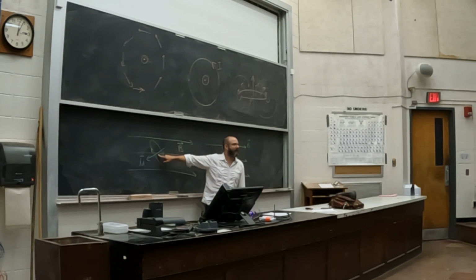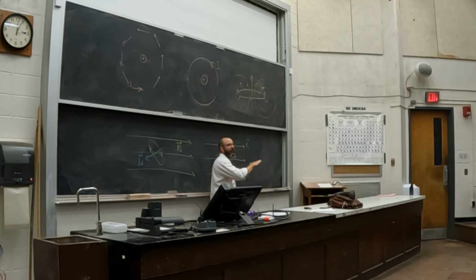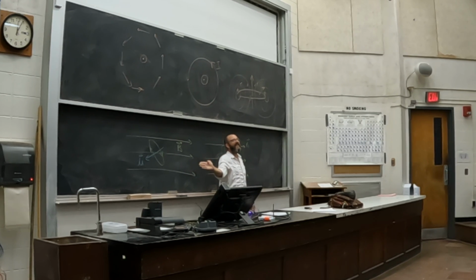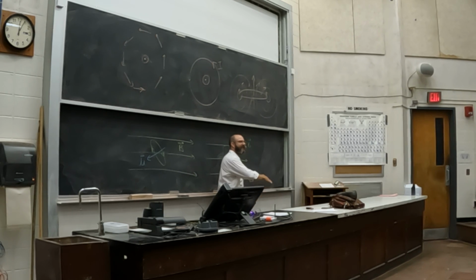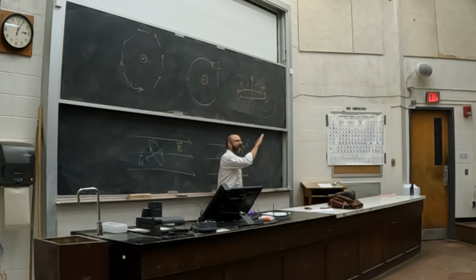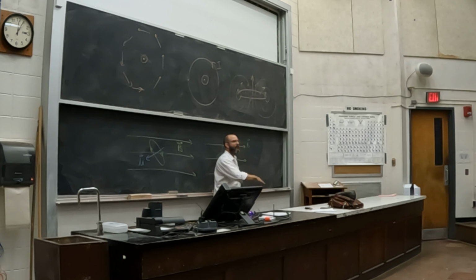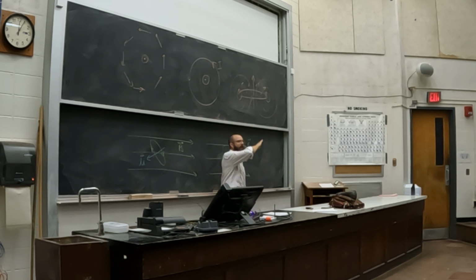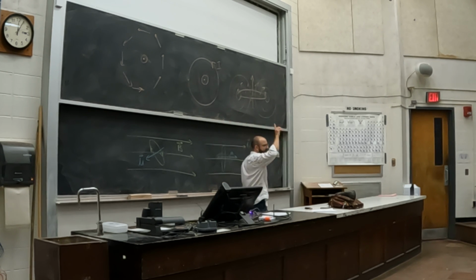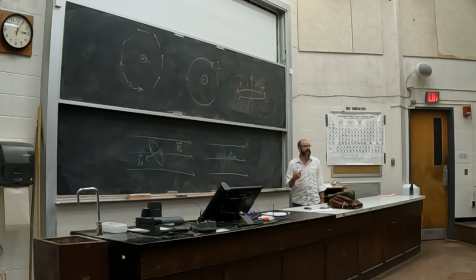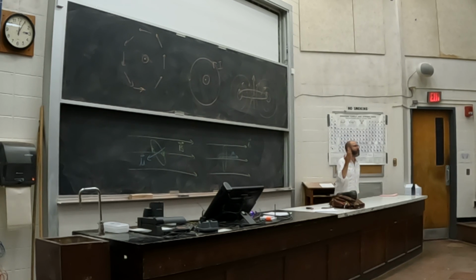now, right? This thing then by its own inertia continues to go to here. And then I turn the current back on. And then that gives it a kick to here, and I turn the current off. And it, under its own inertia, goes here. Turn the current on, kick it, off, on, off, on, off, on, and it rotates. Okay. They do that in DC motors by just breaking the circuit.